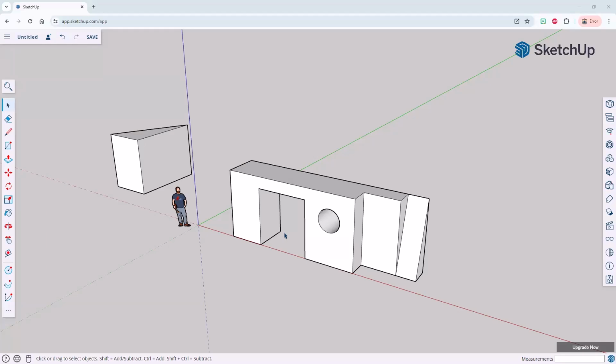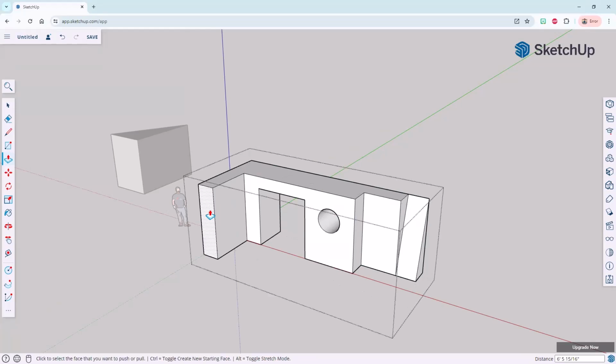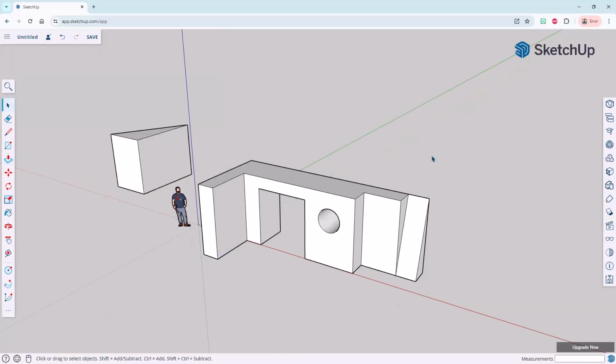Okay, so a question that came up when I paused the recording: what happens here? Do I always have to end up regrouping? And the answer is no, because once I have this as a group, I just double click into it like this. And let's say, for example, I'm going to draw another line right here, for example, this midpoint, and I'll take it straight up. And then I'll go ahead and type P for press pull. And I'm going to take this surface and bring it out in this direction like this. As soon as I do that, notice how the boundary of my group changes. It's part of the group now. So when I'm done, I'll go ahead and use my spacebar and then click outside of it. There's my group. I just went ahead and edited my group.